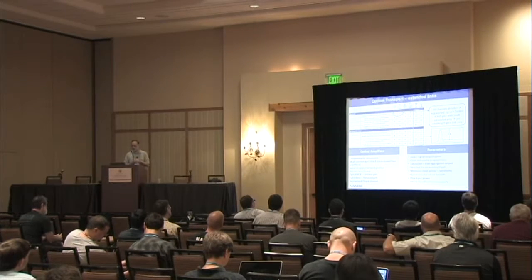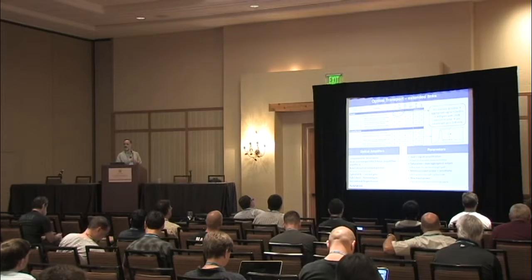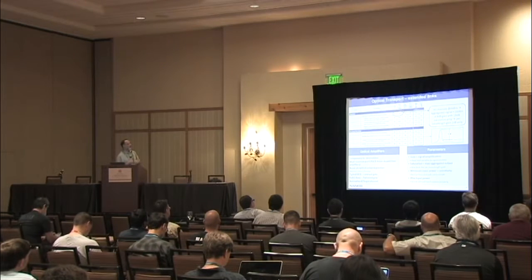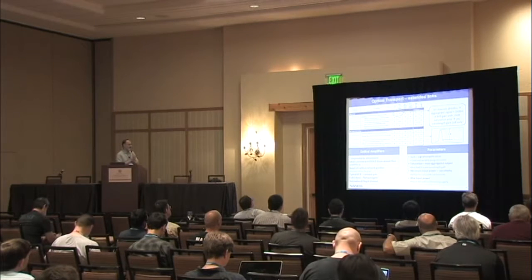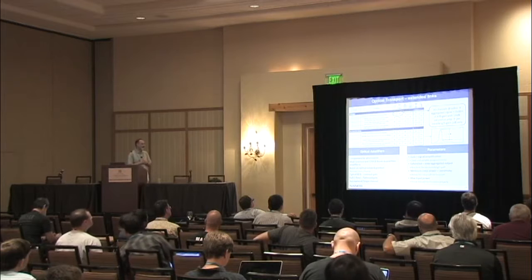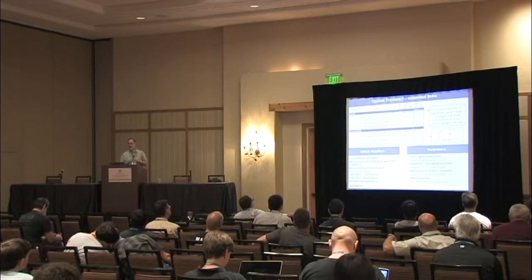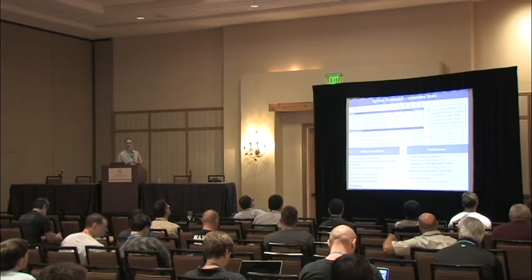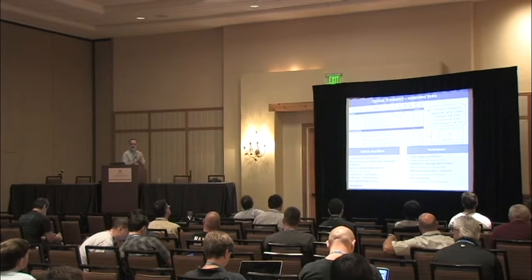Gain is signal amplification, and you can have a fixed signal gain amplifier or variable gain, programmable. Shown there in red are basically two parameters, the gain and the saturation. Saturation is maximum aggregated power. So regardless of how many wavelengths you have and what your gain is, you are going to saturate. That's the maximum output that you are going to get out of this amplifier.